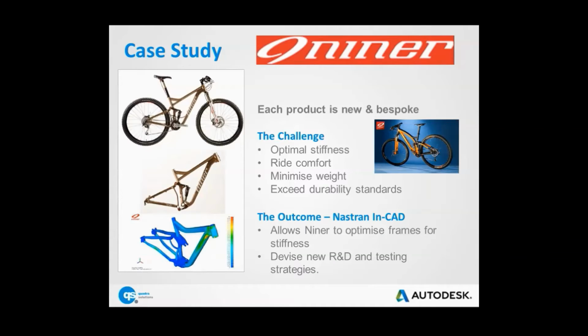Nastran, because of its track record and the versatile range of analyses that fit the bill, is now used integrally from the beginning of each design stage to refine the frame stiffness and the ride specs during the in-CAD design process, whilst shaving off those precious grams of the chosen composite materials in the process. And it's important to mention as well, these are composite materials that are being simulated and analysed within Nastran as they're going along. All this without compromising the actual strength and durability of the product.